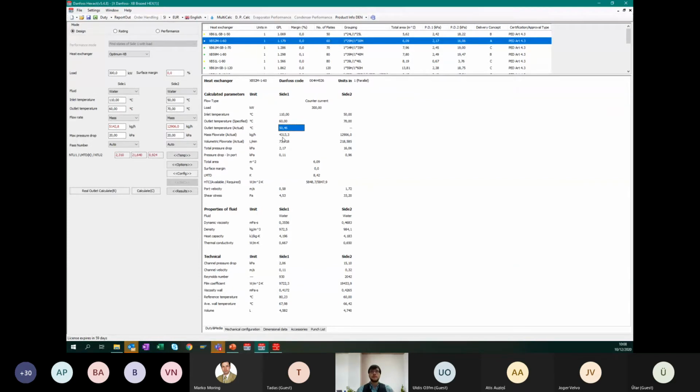So in that case, my surface margin, which was 100%, is actually a full benefit to the district heating network, because I am providing back to the district heating a lower temperature than they want, so below 60, and I'm actually using a lower flow rate from the district heating supply system.